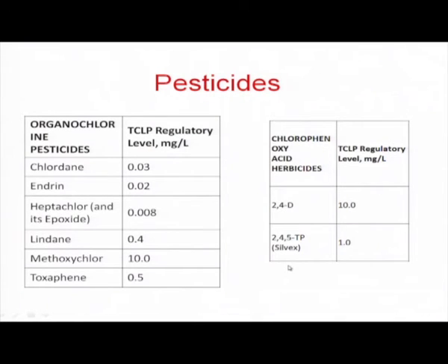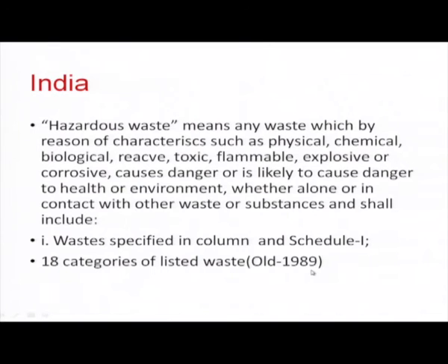So, any hazardous waste arising should be checked for TCLP procedure and compared with the limit, and then it should be decided whether it is direct fit or it should be stabilized further before disposal.